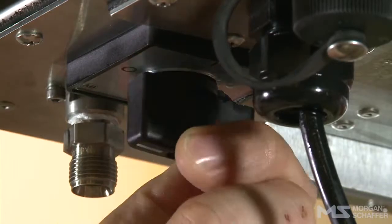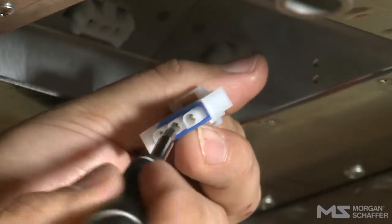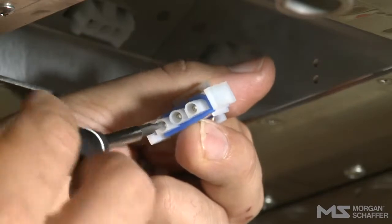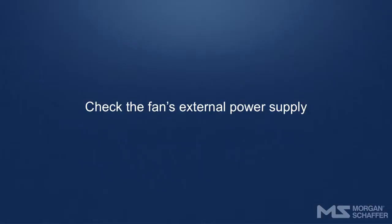Turn off the Calisto. Check that the connector's male and female pins are in good contact and that the connectors are clean and in good condition. If not, clean and/or repair them. Check the fan's external power supply.